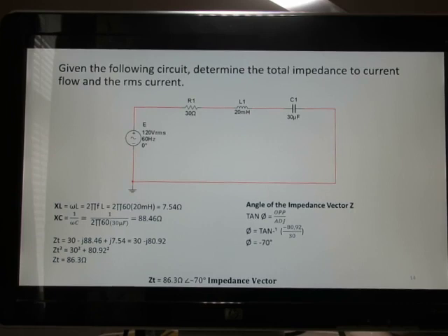First, as rectangular coordinates, we write out each in ohms because we can add and subtract in rectangular coordinates, and we divide and multiply only in polar coordinates. So we need to be able to go between polar and rectangular systems. Rectangular coordinates here would be R is 30, that's a real number, but X sub L is an imaginary number, and it'll be positive J, and X sub C would be a minus J imaginary number. We use J in electrical engineering because I is used for current.